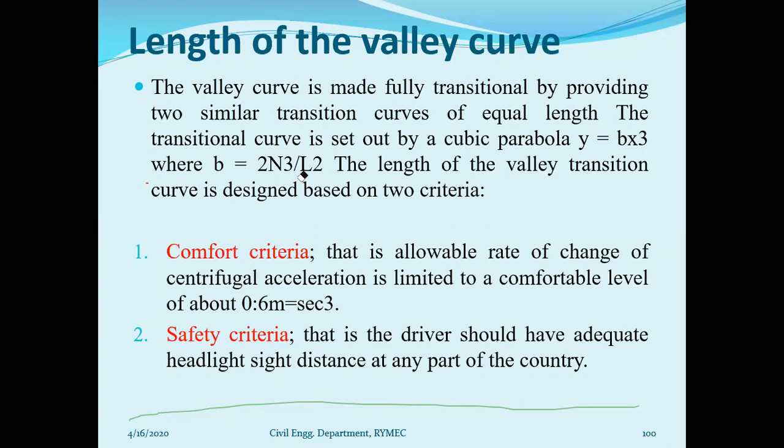Safety means, definitely, we are talking with respect to the night. During the day we can easily see the whole length of the valley curve, so during daytime there is no problem. This safety purely depends on your second case, that is your night sight distance. For that night only we are providing this safety criteria.